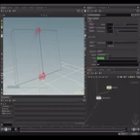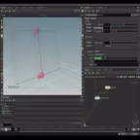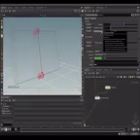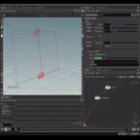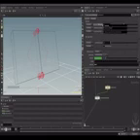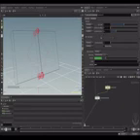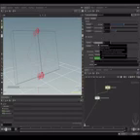Let's go back to the data options. And these are the values by default. If we hadn't overridden the rest length, this will try to set the distance between every constraint to this number here. The error reduction parameter is how hard the pieces will push or attract each other to reach this length in each step. And this means that these constraints are sub-step sensitive.